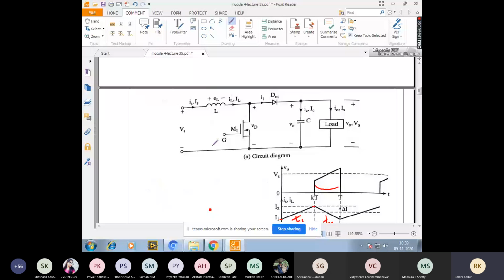By this time you have separated your source and the load, because here it is not connected. The load is bypassed from the source, yet it still gets current from the charge stored in the capacitor, so you get a continuous flow of current to the load.